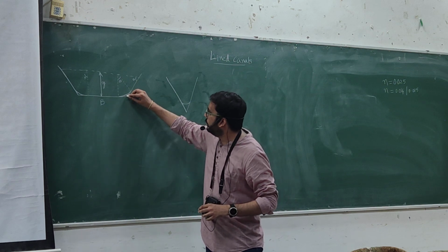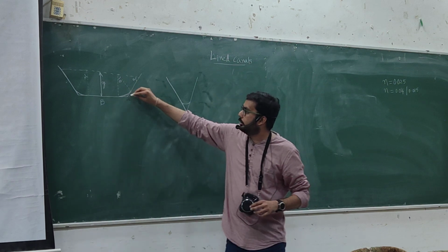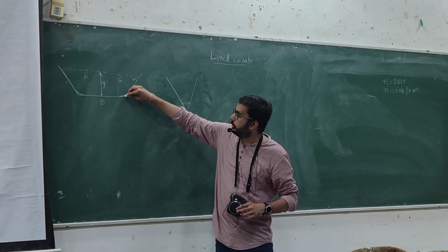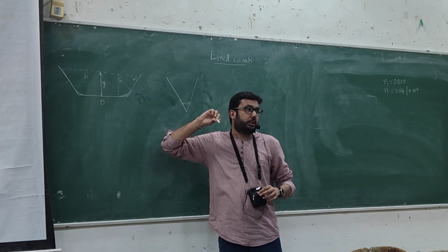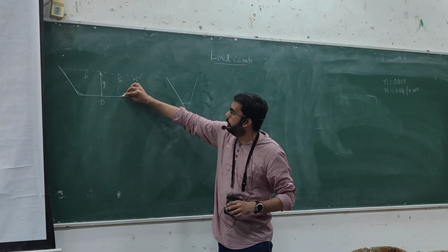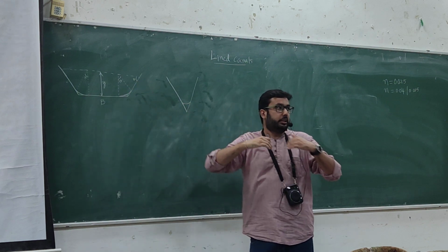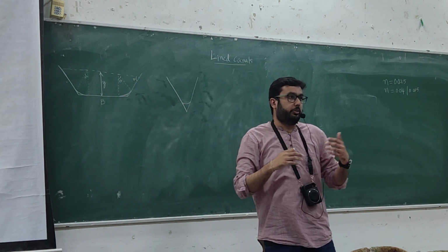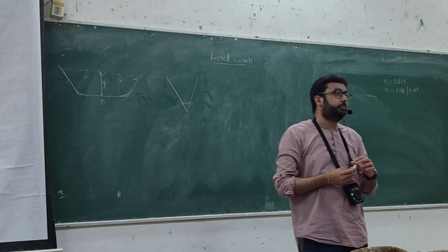If the velocities are high, at the sharp edges we may start to see the sediment eroding. To avoid that, we increase the wetted perimeter so the velocities on the borders are slightly reduced, and we can protect the corners from erosion.